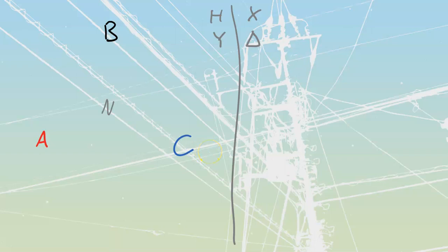And now we're going to take a look at our actual connection and say we're looking for a Y type of connection. So if we're looking for a Y type of connection, we're going to start with A, and we are going to feed in. Now, like we have done in the previous two videos, Y-Y and delta-delta, we always start on our high side with the H1 of the associated one that we have.